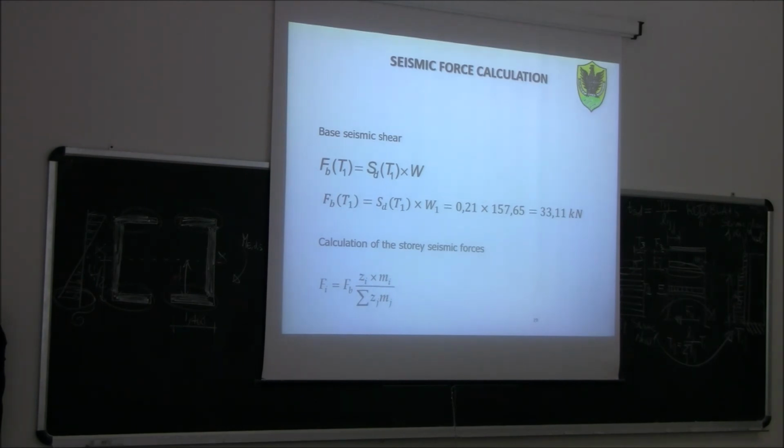The light frame building is significantly lighter than a cross-lam building. So when we design a light frame building, we design for seismic, but strictly speaking, we should also be designing for wind, because wind may govern the design. Why may wind govern the design? Because the light frame building is lighter than the cross-lam building, first. And the q factor is higher than for the cross-lam building. So the value of the seismic action in a light frame building, since I use a q factor of 5, will be half that of the cross-lam building. Even lower than half because the building itself is lighter. So it will probably be 1/4.